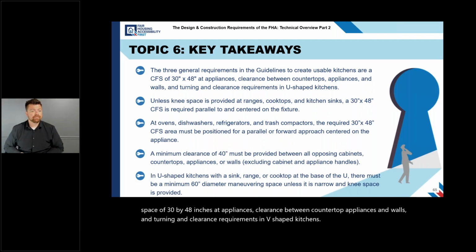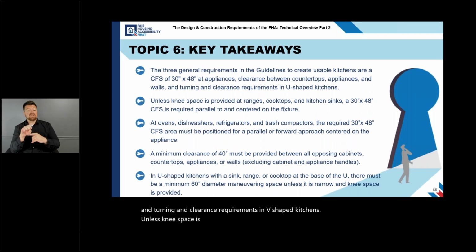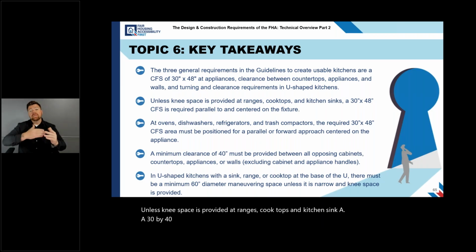Unless knee space is provided at ranges, cooktops, and kitchen sinks, a 30 by 48-inch clear floor space is required parallel to and centered on the fixture.